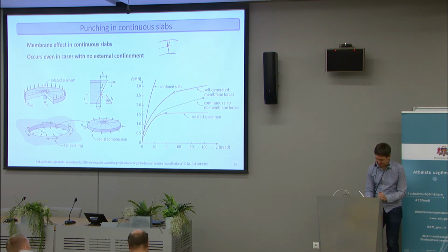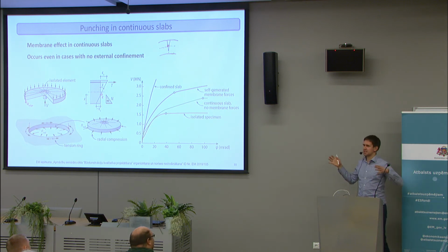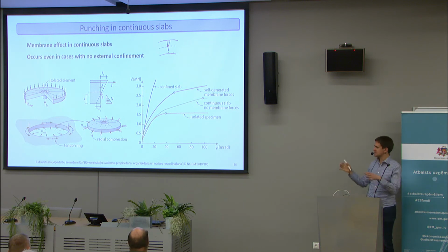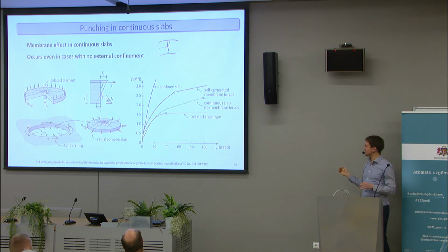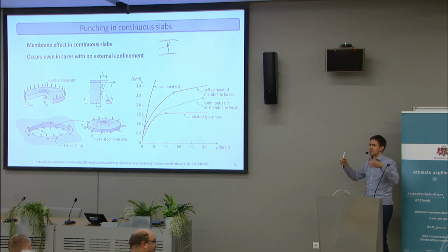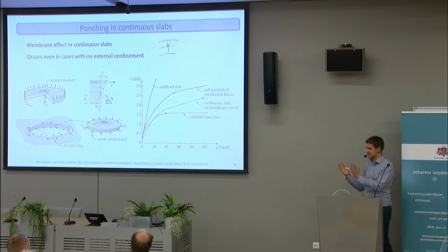And this restricts the expansion, which means it generates compression that creates a compressive force in the hogging moment area, or negative moment area. And if we take this into account as well, we see that it's basically like pre-stressing, where you add normal force, so you delay cracking, you increase the stiffness against cracking, and reduce the curvature.